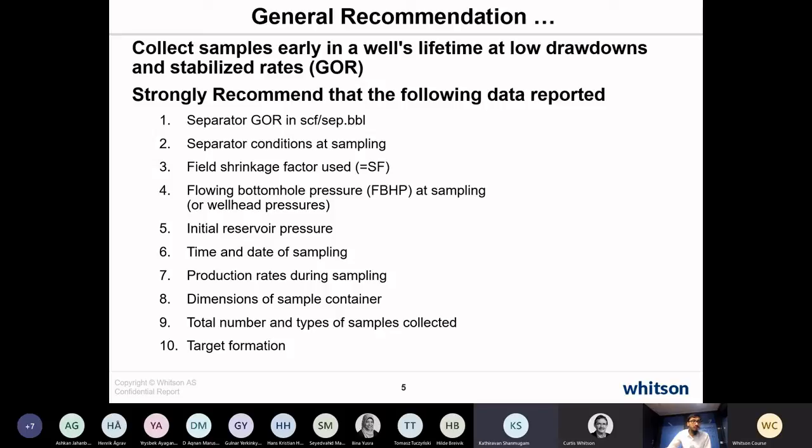Yes, one more thing. Thanks for the clarification on the water. The one more thing is actually regarding the solids present. Sometimes what I've read is the solid particles can act as a stabilizer for emulsions in case there is an emulsion forming tendency. In that case, how important is it to sample for the presence of solids in the reservoir, or where it is there?